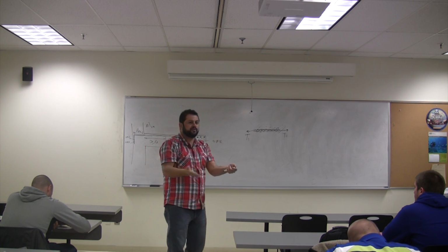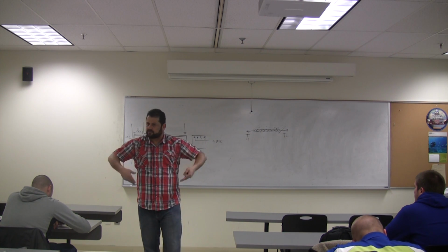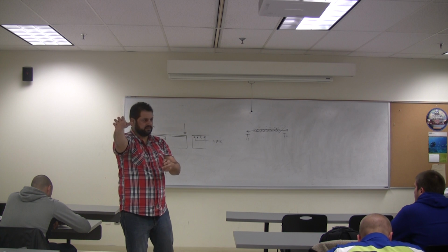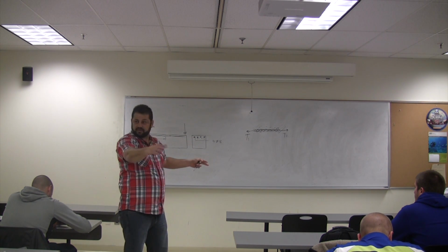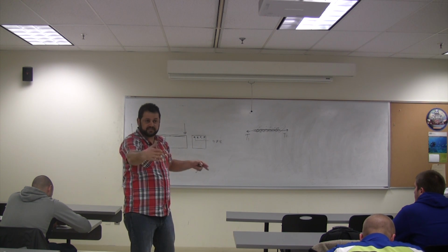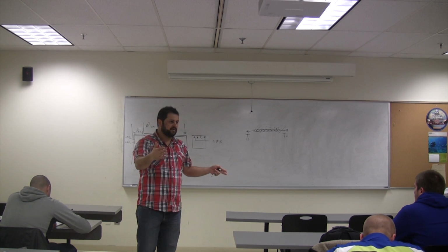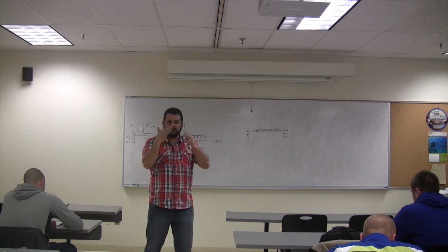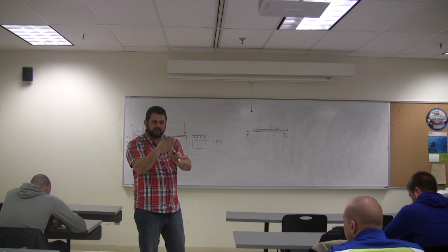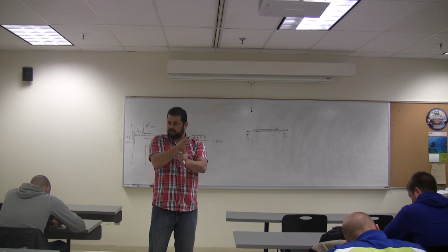If you have a beam with 16 bars, are you going to continue the bars all the way? Of course not. The moment will be 0 at the end. It's decreasing if it's simply supported. So you may cut half of them at different stages, depending on the length of the beam. So the answer I want to tell you: we can terminate some of the bars when we no longer need them, when the rest is enough.